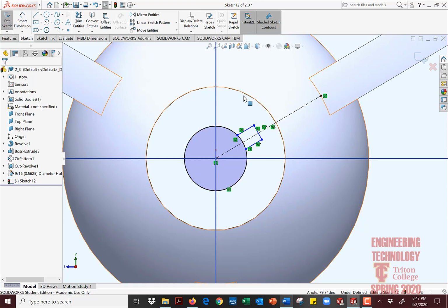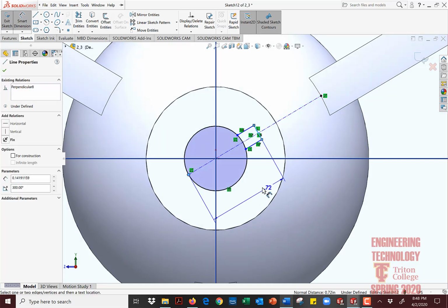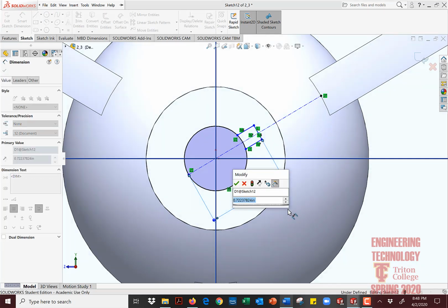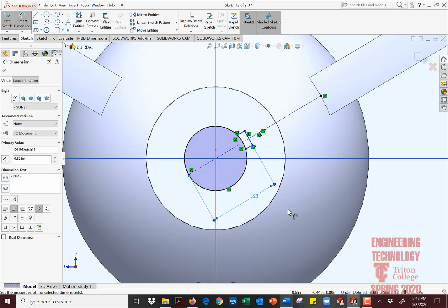So we want it to stand out 5/8 of an inch, but you'll notice that your center line ends here. So what you can do, you can go ahead and extend the line. Okay. So you see how when you click on your little trim option here, you have extend. So I'm going to extend that line to drop all the way back here. Okay. So I can dimension from here to here. See that? And I can just type in 5/8 and it'll do the math for me, make it 0.63.